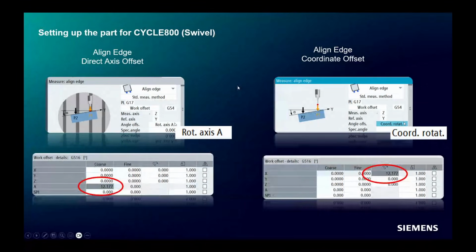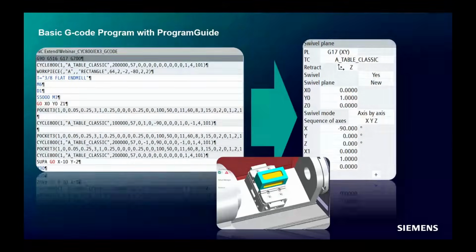All right, so now that we've gone through the basics of aligning for this whole tracking, now we want to take a look at what a part program would look like. I always see a lot of value when I'm first getting my head around commands like this in just hand writing a real simple G-code program that will start to show us some of the cycles and functions I would use to support this. So in our case, we're going to do a basic 3-sided part path, single tool. We're going to make 3 pockets on 3 faces of the part. I'm going to show you how to step through that beginning to end, and we'll be able to simulate it and run it.